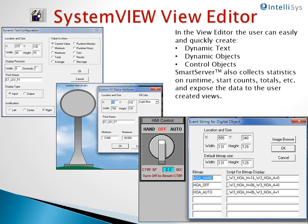We see that when we look at the dynamic text configuration. Even for a digital input, you can keep statistics such as runtime hours, runtime minutes, sets, and resets. That type of information can be used for displaying accumulated runtime on a motor.